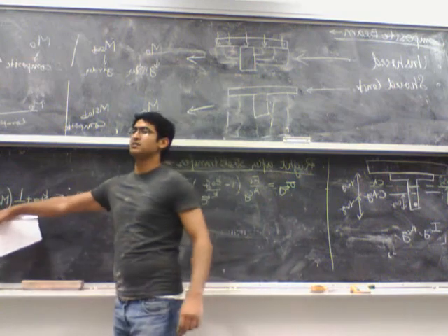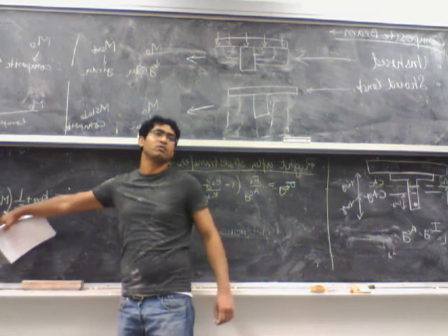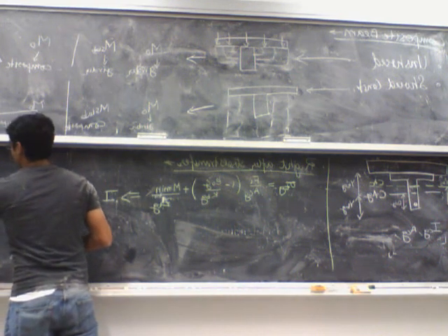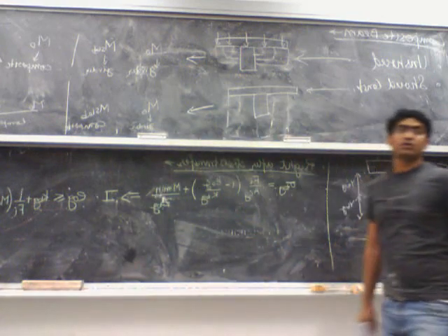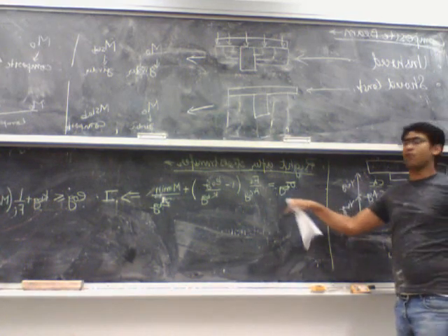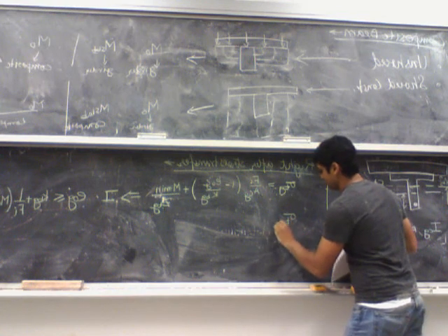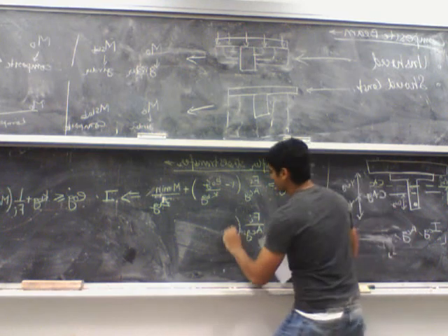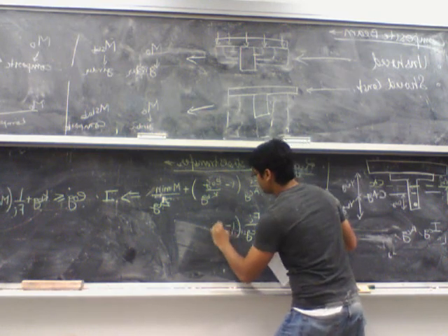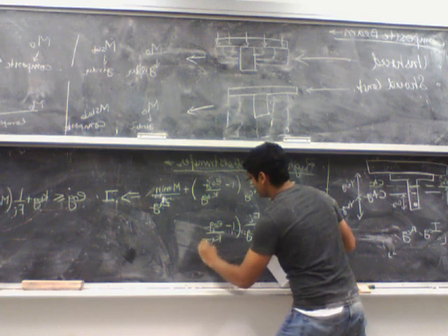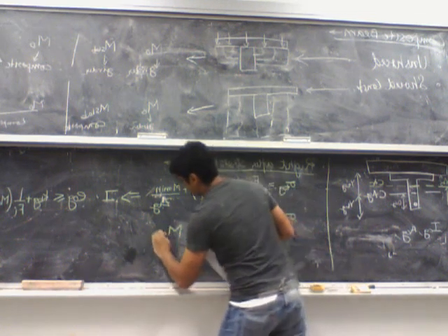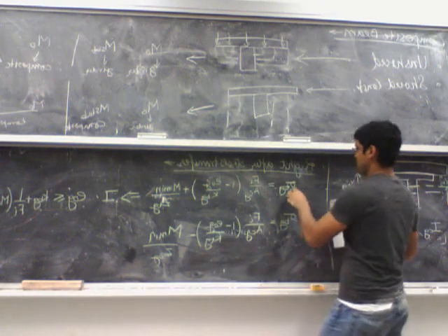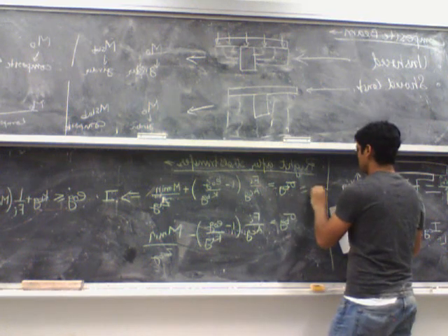What is M min in this case? M min is nothing but the moment due to the self weight of the girder, because there is no other load acting on it. So this is simply M naught of the girder. Similarly, I can write the stress at the bottom, and this becomes Fi over ACG, 1 minus E naught G over KG, minus M min over ZBG. Actually, I forgot to write something. And this is top. This has to be greater than or equal to sigma t.